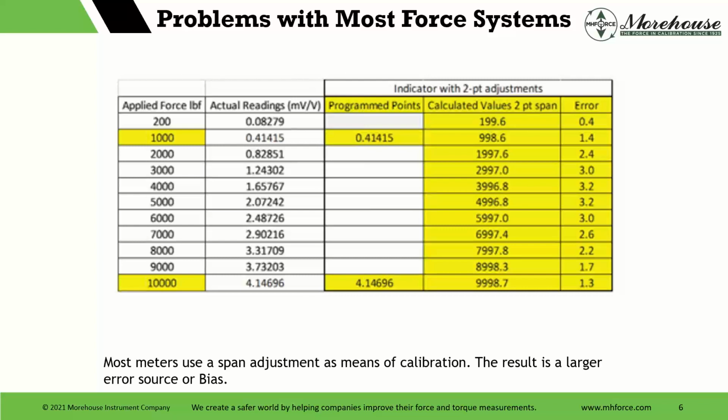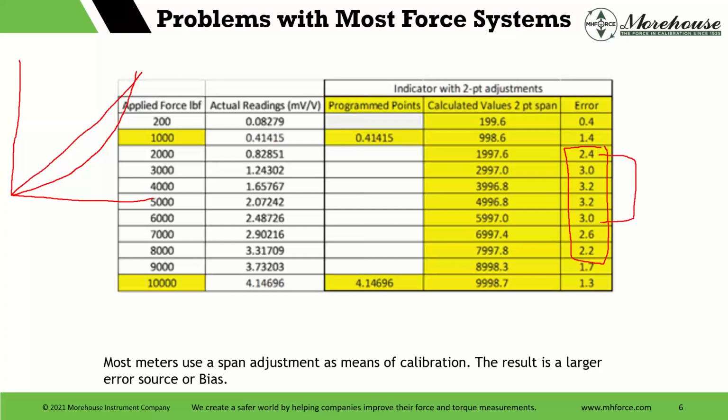But in the middle, what happens with load cells is they're generally not linear. And this is where I get the fun with doodles, because my mouse works, and you say, I have a straight line. What are we talking about with linear behavior in load cells? Most load cells are going to do something like this, where they deviate from linear. And you can see that linearity is going to be the worst at like 20 to 40%, 20 to 60%. At 20 to 60%, you generally have the worst numbers, and that's this to here.